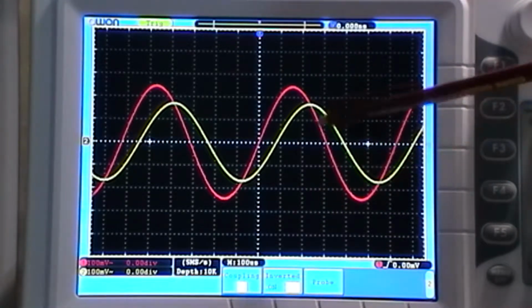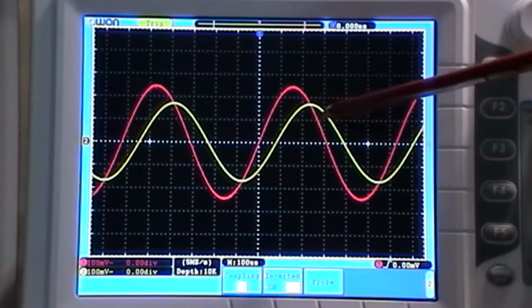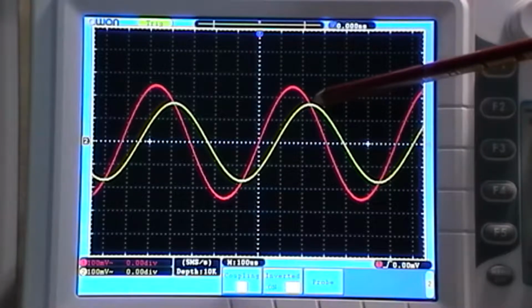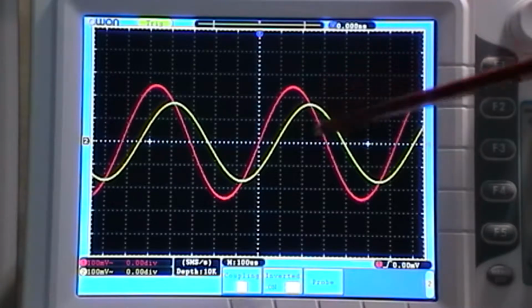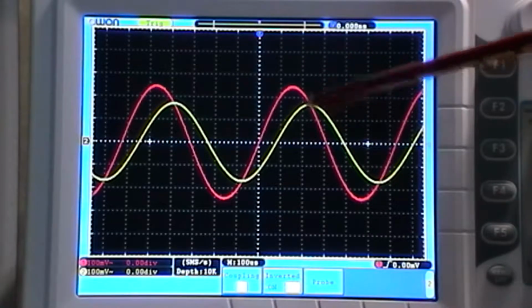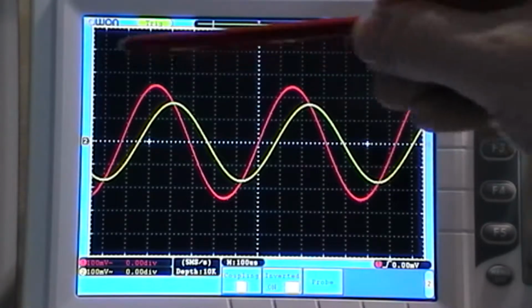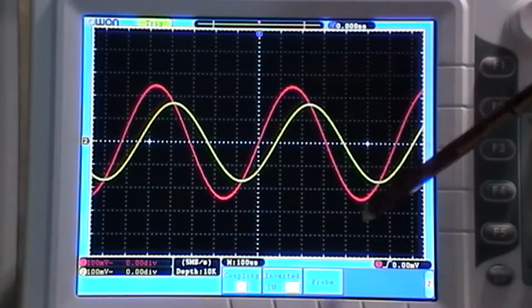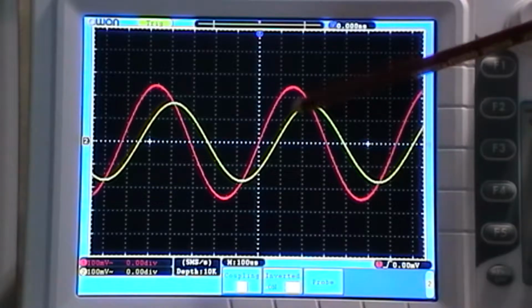And on this occasion, with all these passive filters, when I reach the point at which it starts to attenuate, I'm already at -3 dB on the frequency at which we started, which is 1.6 kilohertz. There is a calculation.